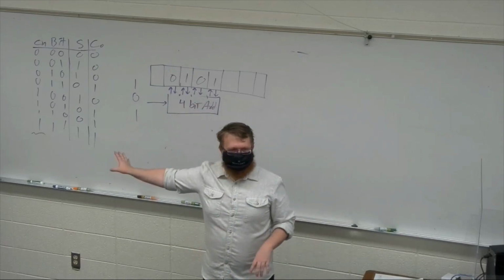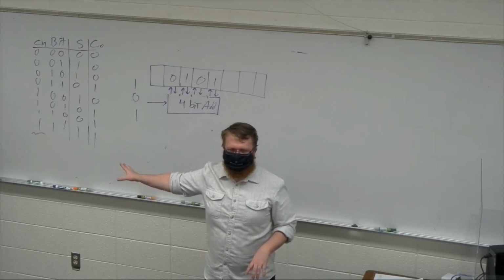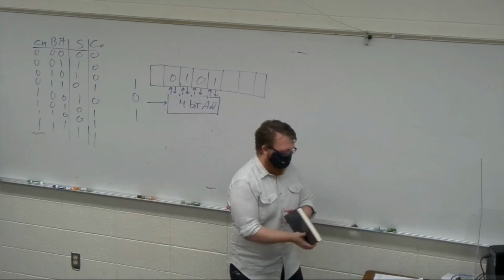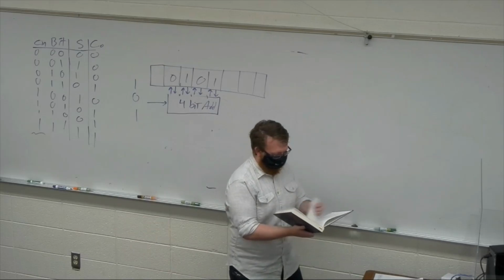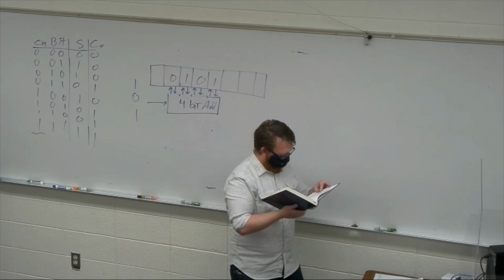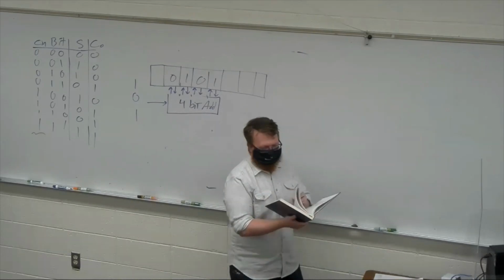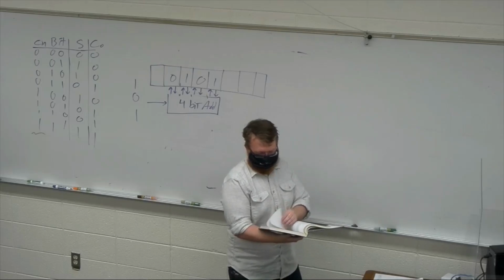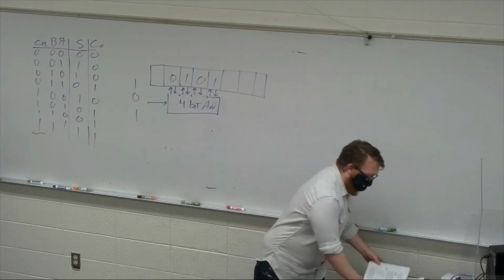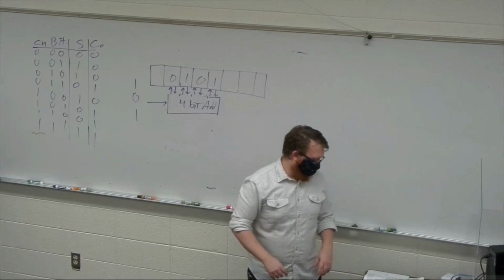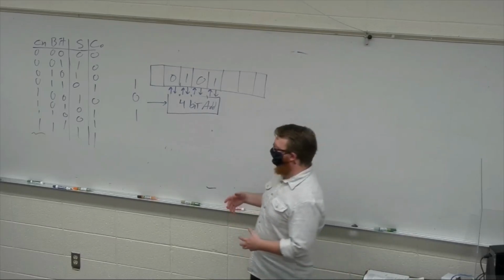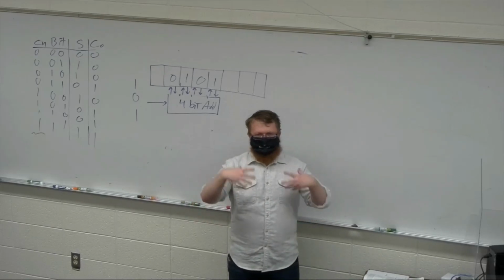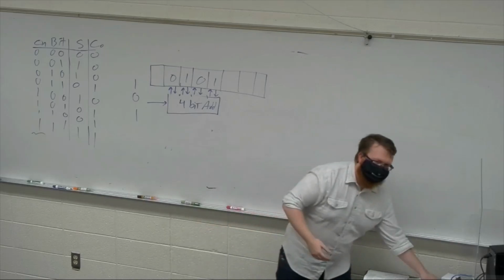Everybody get the shift and add? There's the example in your book. There's actually a whole bunch of other ones that can do for multipliers in there. Actually, there's going to be one more, isn't there? But it's stupid. And by stupid, I just mean easy. This is what they call the array multiplier. The array multiplier is really easy. It just takes advantage of the fact that we have a cascade of additions, and it uses similar logic to the carry look ahead.